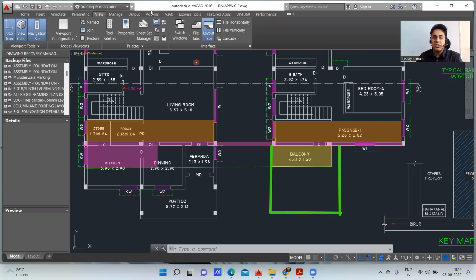So that is the reason you can see it is only up to here, because this is only this much cantilever I can take. I cannot take a cantilever like this. If you take a cantilever like this, then the thickness of your slab will be huge. So in order to reduce that thickness, we can only give this much cantilever, which is 1.50 meter, roughly around 3.5 feet, and that's a good cantilever length. You can keep it. Great.